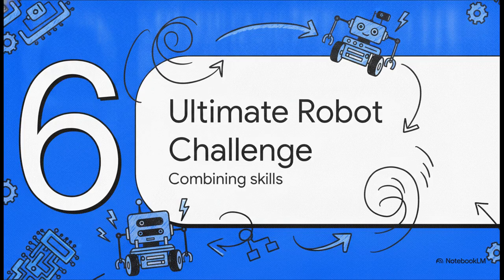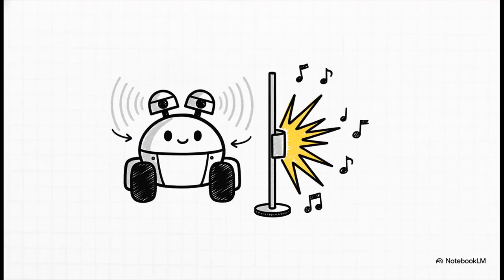Section 6, The Ultimate Robot Challenge. Here we go, the final objective. The challenge? Combine ultrasonic obstacle avoidance with a touch sensor fallback that stops the robot and plays an error sound. So what does this mean in plain English? You need a primary loop using the ultrasonic sensor to steer away from walls, exactly like our Roam flowchart. But you also need a backup plan, a second layer of logic, another switch.